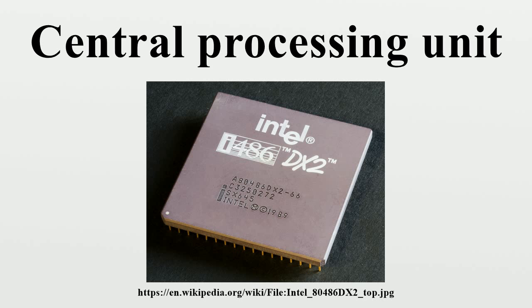These flags can be used to influence how a program behaves, since they often indicate the outcome of various operations. For example, in such processors a compare instruction evaluates two values and sets or clears bits in the flags register to indicate which one is greater, or whether they are equal. One of these flags could then be used by a later jump instruction to determine program flow.